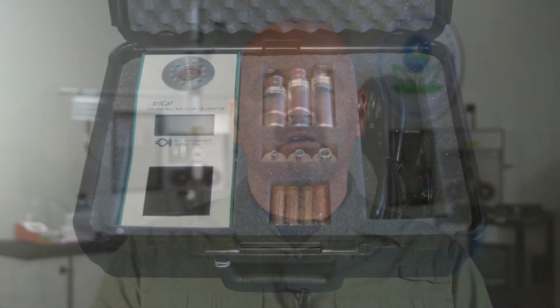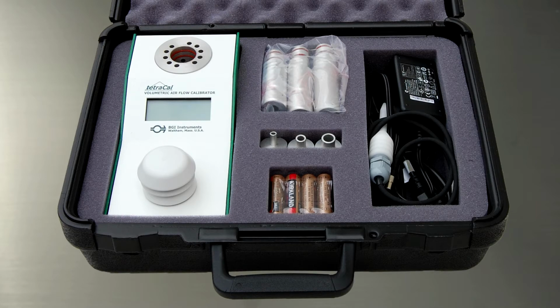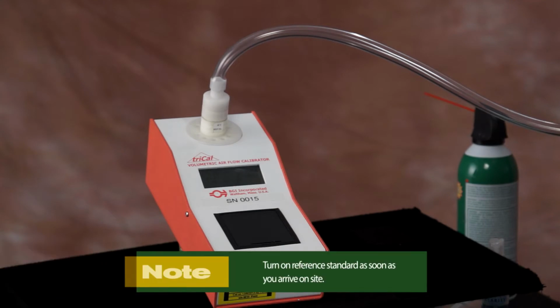To perform the calibration procedures, a NIST traceable reference standard that has a flow value range of 10 to 20 liters per minute is necessary. Typically, either the BGI Tri-Cal or Tetra-Cal are the standards of choice, though some still use a Delta-Cal. For this demonstration, we are using the BGI Tri-Cal as our reference standard. When in the field, always turn on your reference standard as soon as you arrive on site.